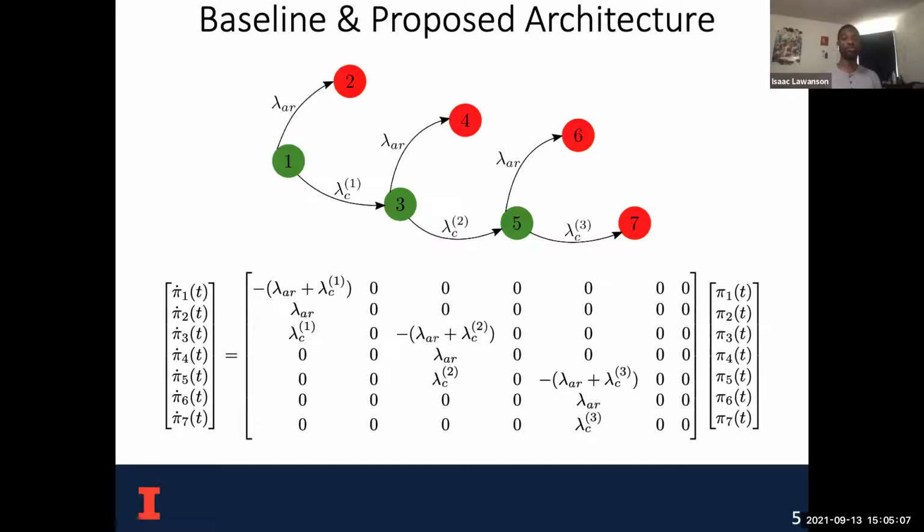This next slide shows a representation of a Markov model showing the possible states of the system and the conditions for the transitions of those states. So we have state 1, which is when the converter is working exactly the way it's supposed to. And then we have state 2, which is if any of the switches or if any of the diodes fail, then the model goes to state 2. But if the capacitor just degrades to that first level, then we go to state 3, and then from 3 to 4 if one of those components fails, and so on and so forth.